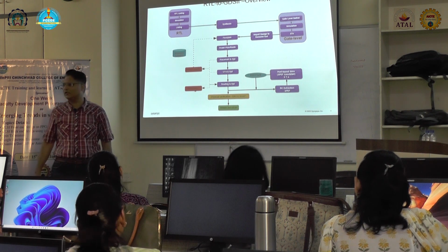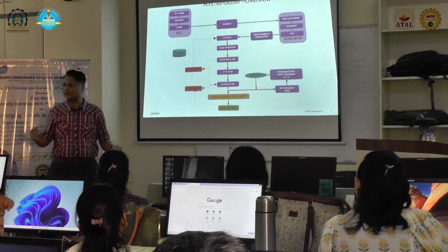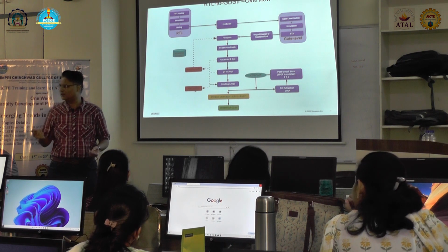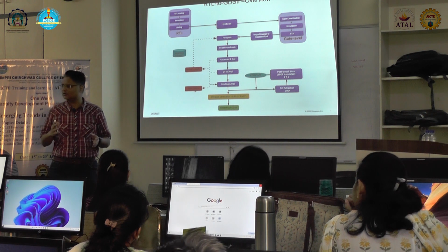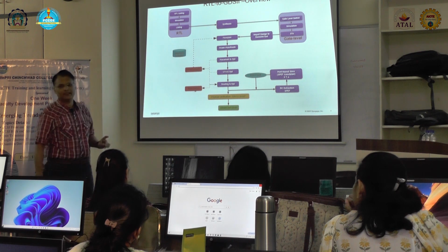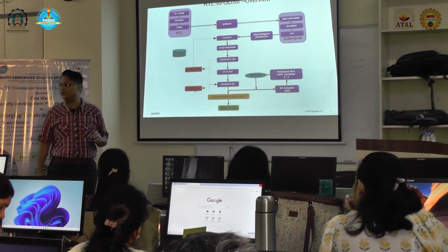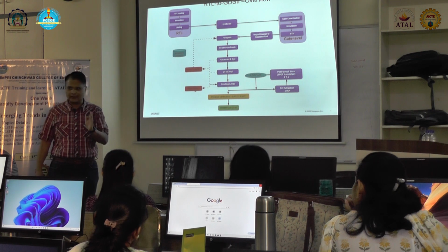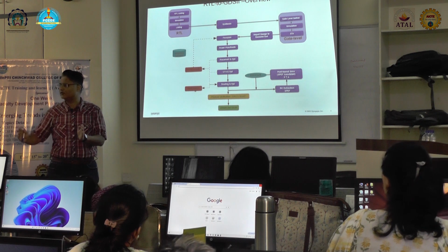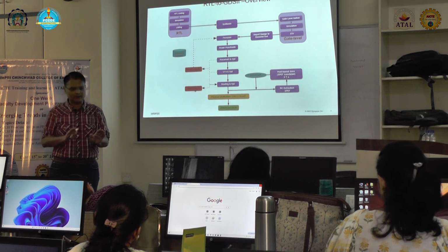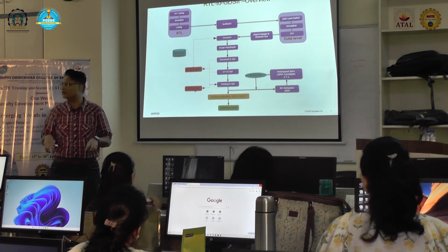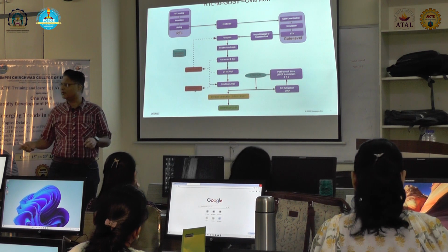So if a million gates start simultaneously, what will happen? The 0.8 volts will trip, right? So you cannot start the entire chip at the same time. Power integrity has to be performed to make sure that you enable power to the chip in stages. You start this part, then this part, then this part, so that the power supply load is not very high. Otherwise, the circuit will not perform.